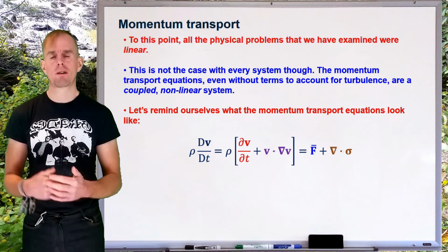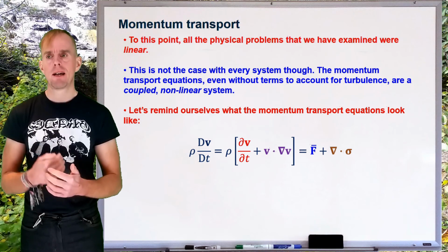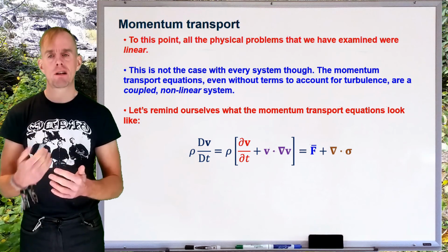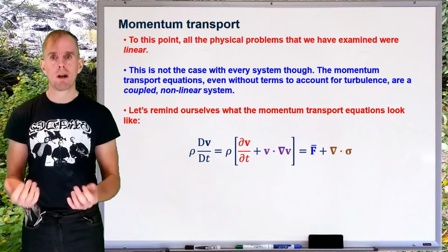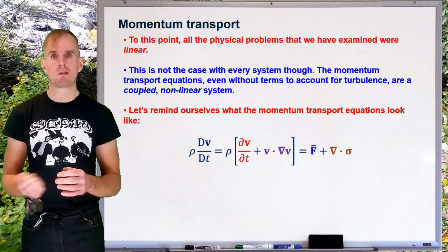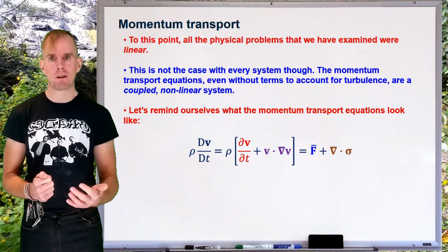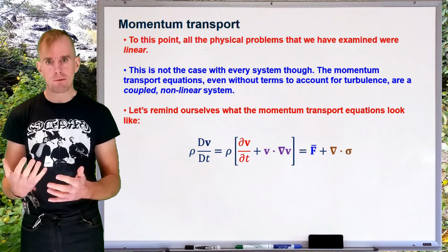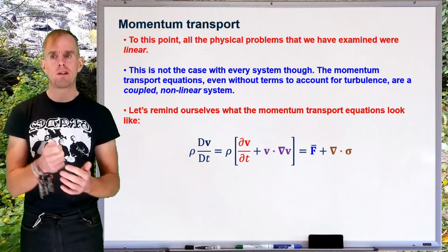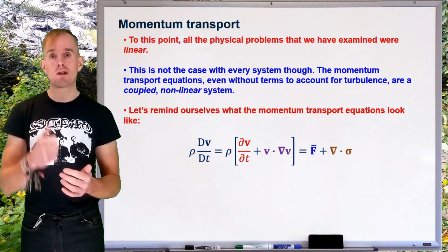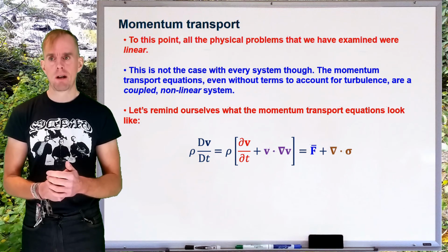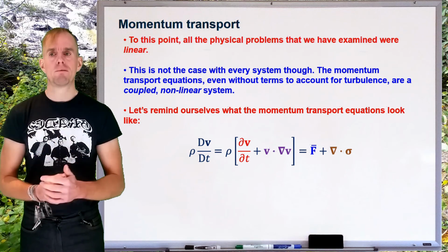We've already acknowledged on the left-hand side that what we have is a rate of change of volumetric momentum. So let's remind ourselves how we relate momentum to force. We've got impulse, force times time, equals momentum, mass times velocity. So force, therefore, is going to be mass times velocity over time from a dimensional standpoint. So that's in effect momentum change, or rate of momentum change. But it's not per unit volume.